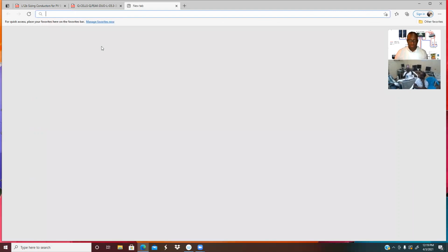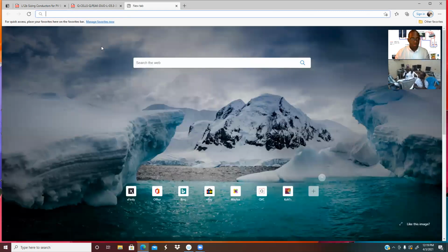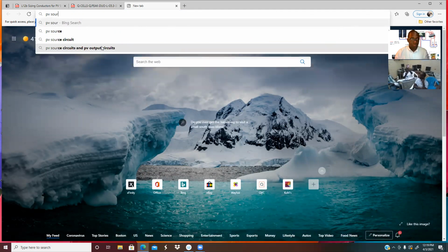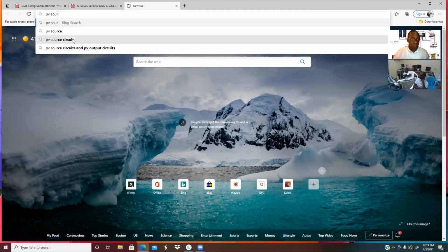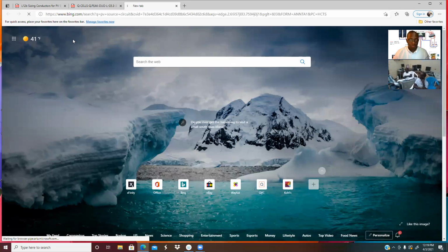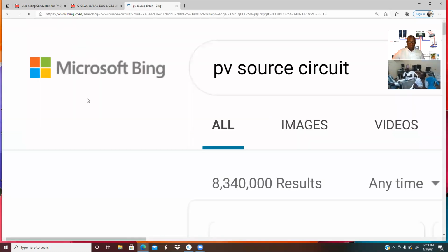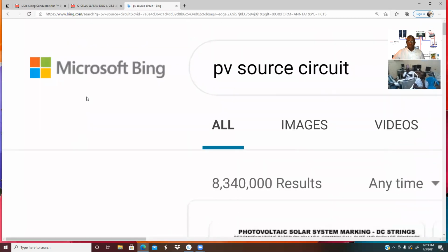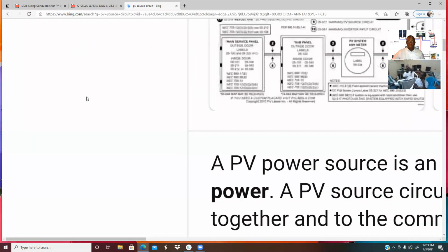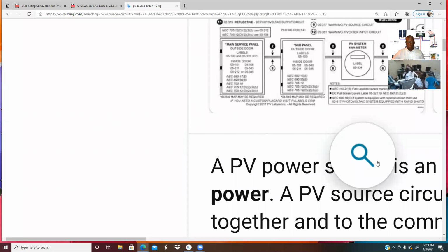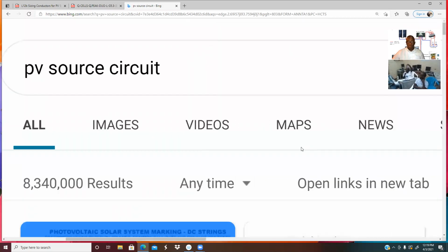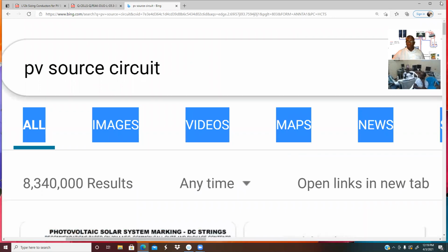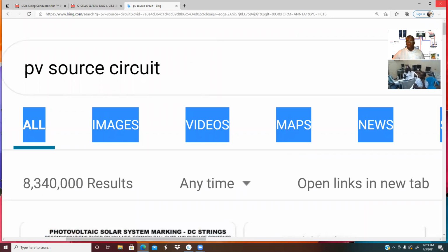That first one helps us to determine the current from the array to the circuit. Now the second one, the 1.5 and then the 1.25, helps me get a better wire size when the current rises, because of the temperature, the wire will have to bear that additional current.